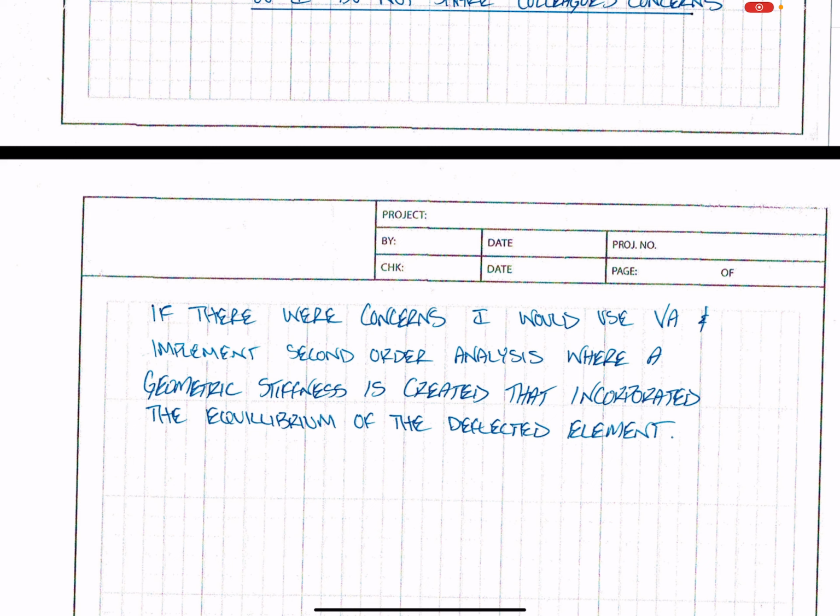But it can also then play a role in P delta. And that's why that check, the stability factor theta, is in the seismic code, right? In ASCE 7, they're taking it a step further and saying, okay, when you go plastic, right, and you start incorporating the Cd value, which essentially relates to the fact that we're doing an elastic analysis, but in real life, this thing is going to be a plastic hinge, so it's really going to displace a lot more, right?